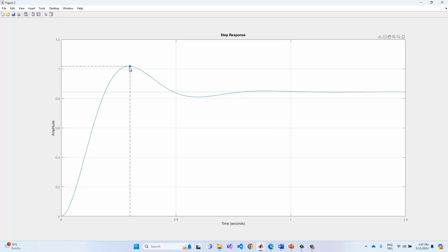properties. The peak response is at 20.7. Okay, and so this is not a second order system, this is a third order or fourth order system, and so it may have a different overshoot value in here, just remember that. And also the peak time is equal to 0.3, right?